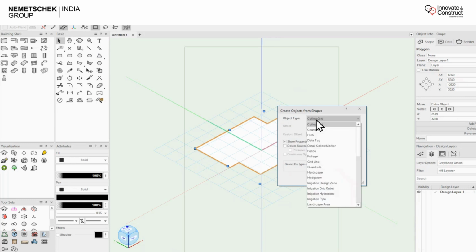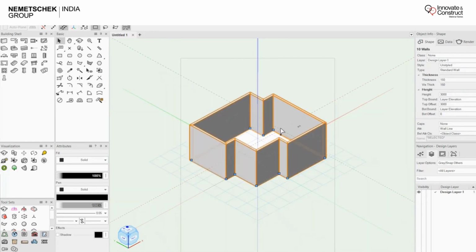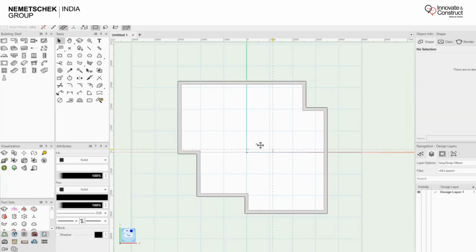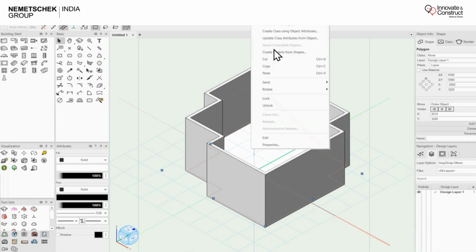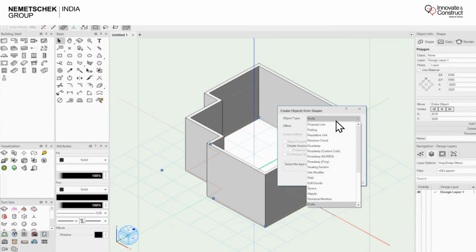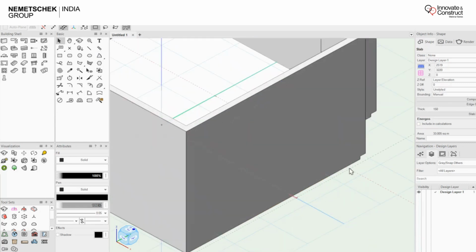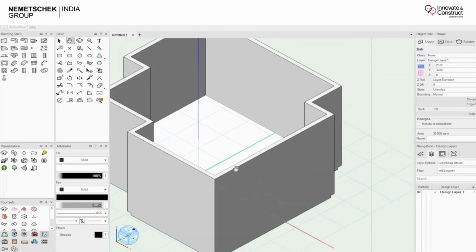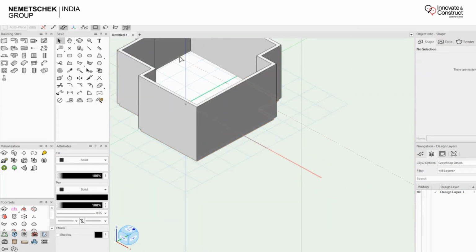You can build your external walls and quickly create your geometry here, and then you have created it. Now once you have created this, you can similarly utilize your 2D space, and then you can create your slab. So you can always go and say slab, and you can create your slab space. So a slab has been created. Obviously, you can further edit it. You can further customize this. Then, if you want, you can use this similarly for your ceiling as well, and further define those into a ceiling space as well.